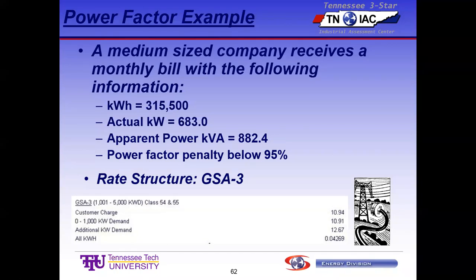But if you average everything over 15 or 30 minutes, you smooth out those individual spikes that only last for a very short duration. So it's to the benefit of whoever's paying the bill to have as large an averaging period as possible. Of course, the utilities always want to shrink it, and the companies always want to stretch it. And then they have to go before the Public Service Commission and make an argument, and the Public Service Commission makes a decision on what they think is reasonable for both sides. So that's kind of how that runs.